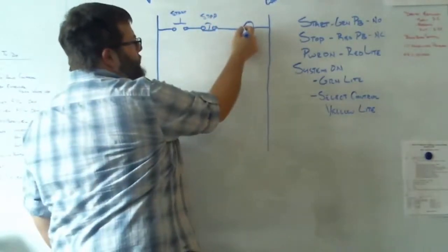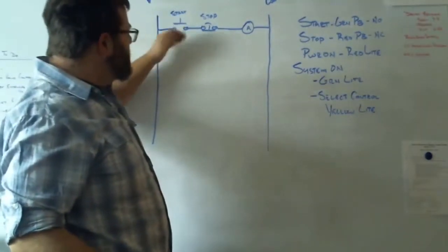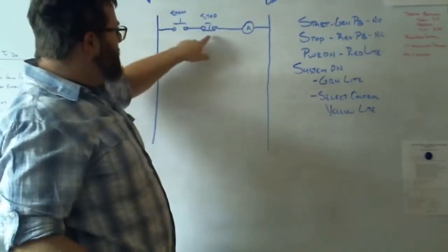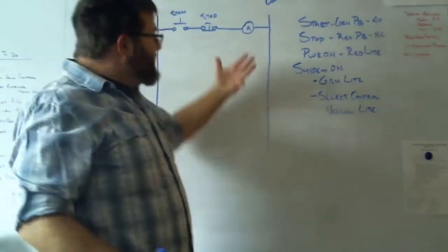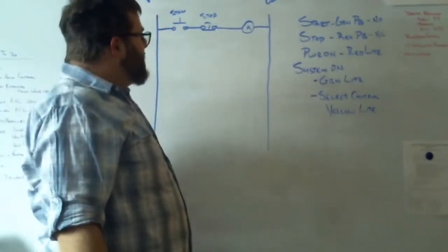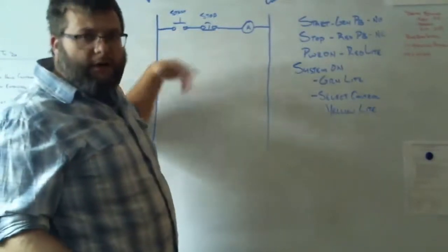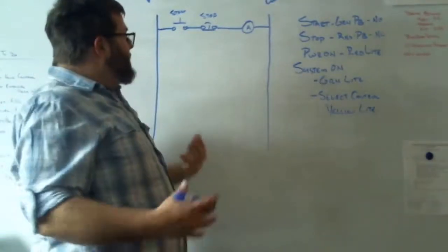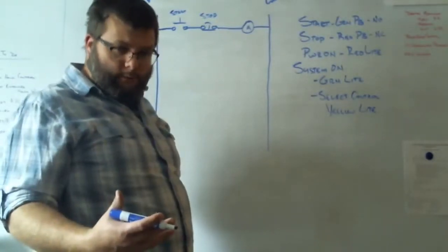Now, as this is drawn, if we were to wire this up, I push this button, it activates. This allows current to flow through, and that coil gets turned on. That is just a relay coil. And that being said, it could run. However, once I release this button, it'll spring back and not run any longer. We need to use a seal, okay?